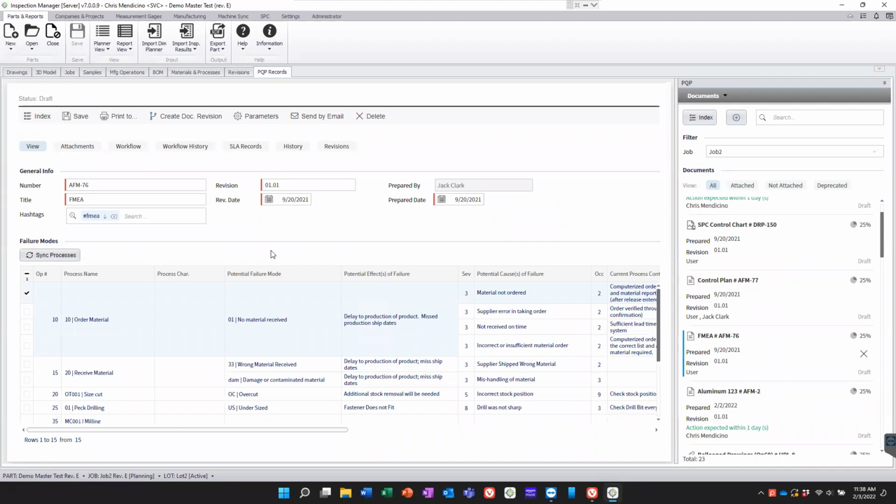And because it's connected with all of the other aspects of your quality inspections, the actual result data coming in, the inspection plan, and so on, you can now actually use an FMEA or a control plan per its original intent. So many companies that fill out FMEAs are really focused on the compliance aspect: my customer requires me to fill out a PFlow, an FMEA, a control plan, so I just do it.